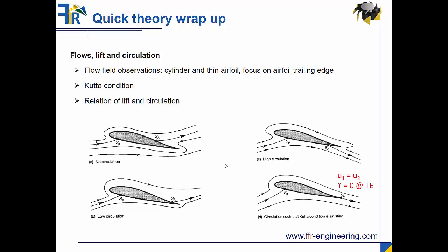And there sometimes you have smoke over the wings to visualize what's going on, and you can really see how the flow suddenly separates and you suddenly have some turbulence. So of course there's a big relation between the angle of attack and the flow pattern. If you have the wrong angle of attack and you incline your plane a lot, then it's not possible to have a suitable flow pattern around your airfoil, and you basically have a separation from the thin airfoil and everything goes crazy.